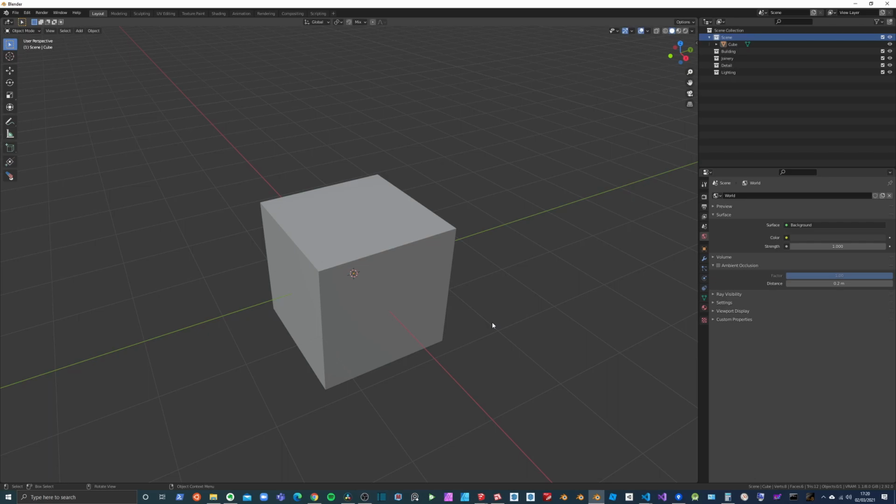One of them is with Extrude. The way that I have built the tool, it's all based around the Boolean operations that Blender has, and I tend to use the exact solver for most of the operations, which is quite new, and I think there's a few issues with it. Sometimes it leaves little bits of the mesh behind which might need to be cleaned up at some point if that happens, but in general it works quite smoothly and certainly works for cutting through meshes.